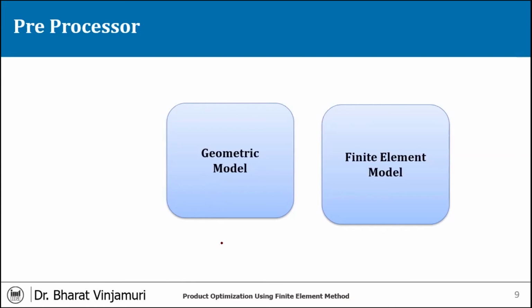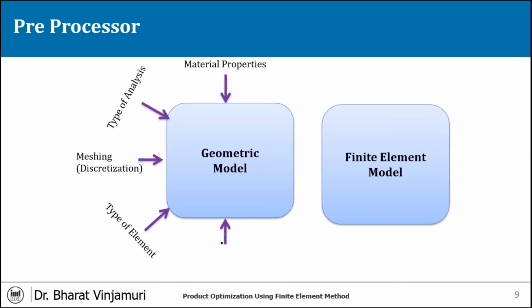the answer is 100% no. The reason is that so many parameters are missing in the model. In SolidWorks, you do not have so many parameters which you need to give. What are those parameters which are missing? These are the parameters which you see on the screen now. These are the parameters which are missing in a geometric model. Loads and boundary conditions I have not given. You have not given any supports to the model which I have made in SolidWorks or some modeling software.